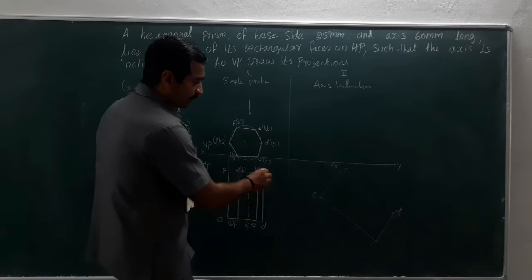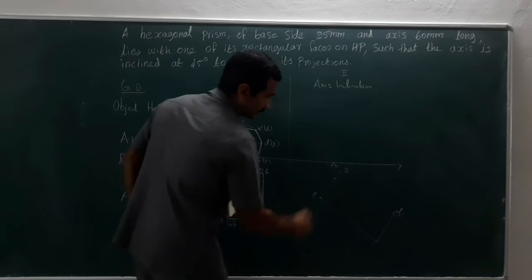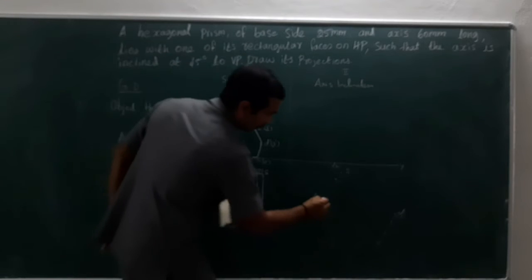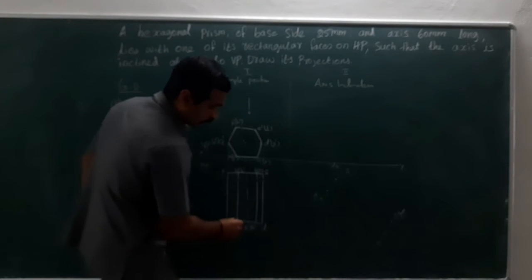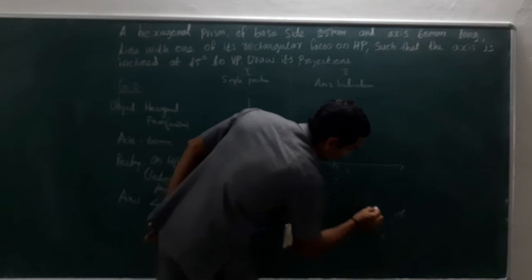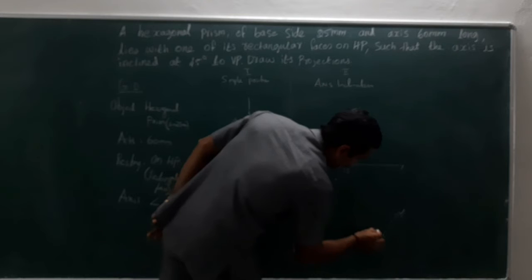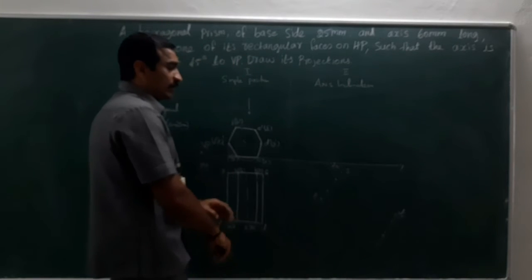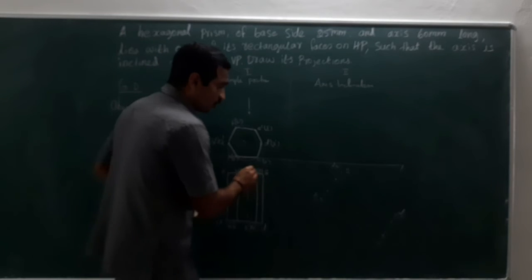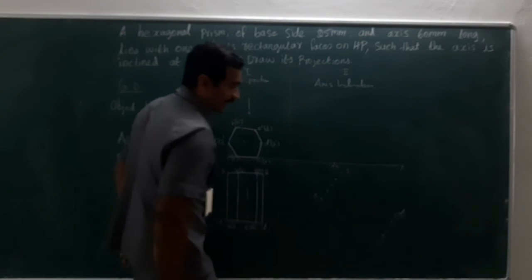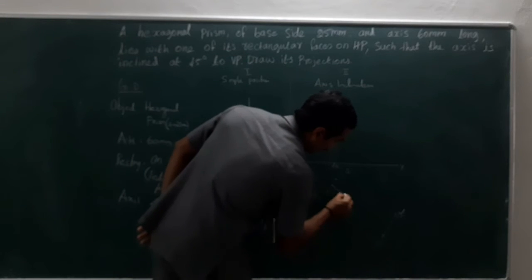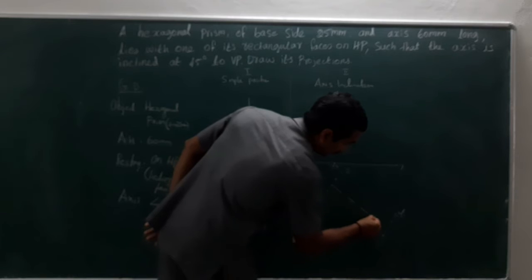Now what is next? Measure from S to T, mark it. D to E, mark it. Similarly, P to U, mark it. A to F, mark it, and draw a line. Initially draw thin lines so that if you make any error or mistake, you can just erase it. Now next, the axis. Measure S to the axis, and D to the axis. Draw the axis line.